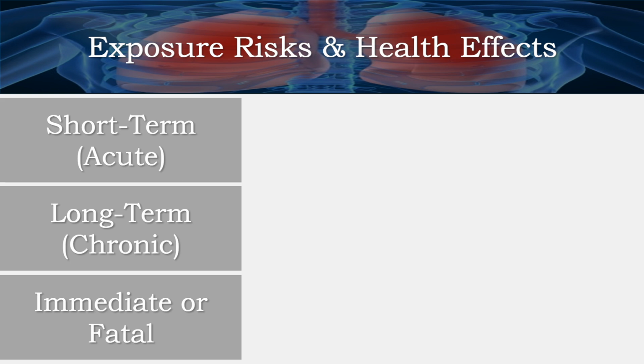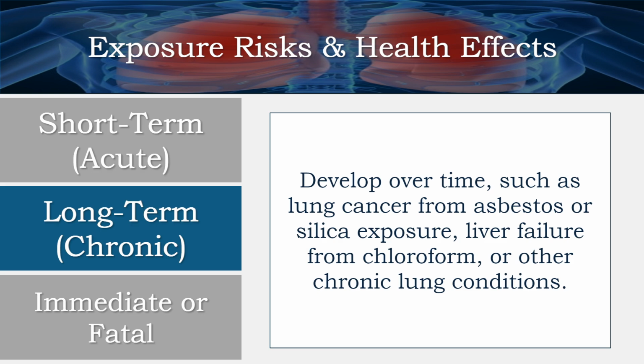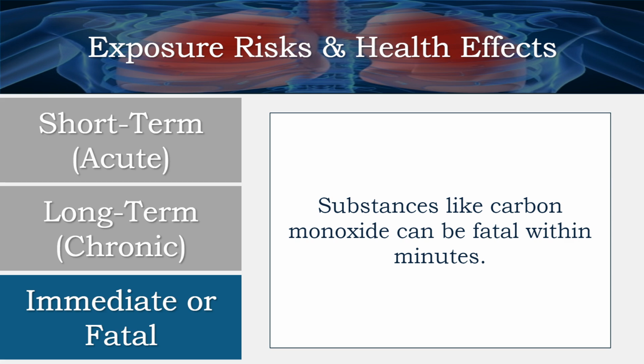Exposure risks and health effects include short-term or acute effects, which can occur rapidly, leading to symptoms like coughing, wheezing, shortness of breath, headaches, and immediate unconsciousness or death from highly toxic substances. Long-term or chronic effects develop over time, such as lung cancer from asbestos or silica exposure, liver failure from chloroform, or other chronic lung conditions. And immediate and fatal hazards: substances like carbon monoxide can be fatal within minutes.